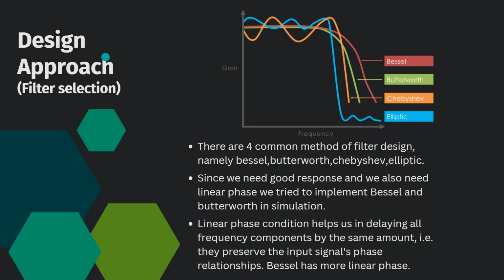And coming to the disruptions caused in the hardware and simulation, we tried to use some different analysis to reduce the issues. First of all we thought about temperature analysis. How does temperature affect the circuit? To ensure whether temperature is affecting our signal or not, we tried to simulate using the Micro-Cap software. In Micro-Cap, we use the temperature coefficients of the capacitance, namely the linear coefficient and the non-linear temperature coefficient.